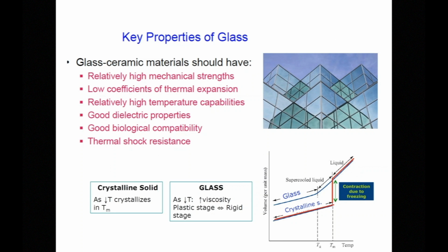You can have a glass transition temperature, a temperature by which, as you heat the glass towards melting temperature, you're actually able to bend it, or it exhibits flexural strength or flow properties such that you can even 3D print glass. And unlike ceramics, which have to be heat cured or make use of a precursor material, glass can be processed directly in the melt.